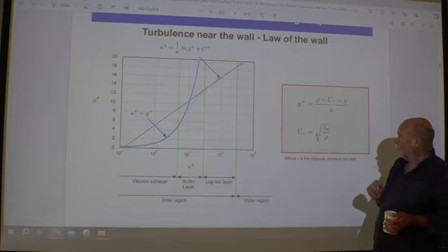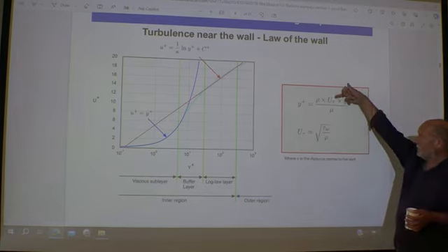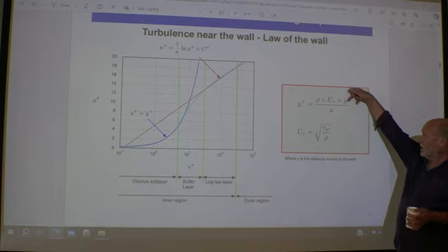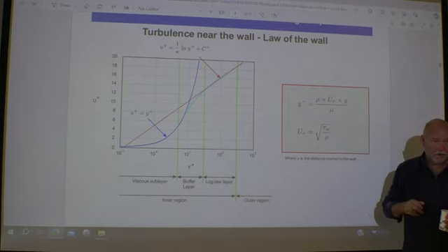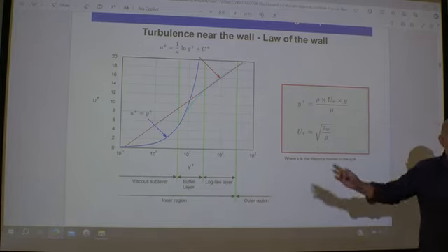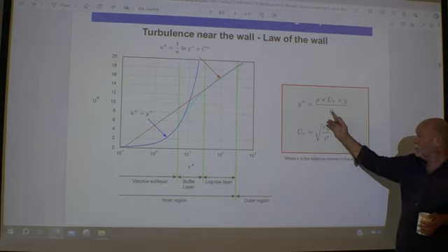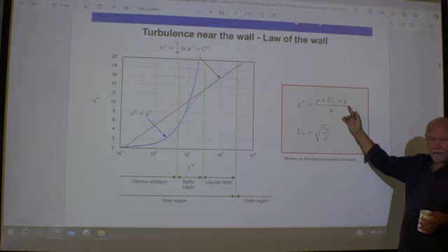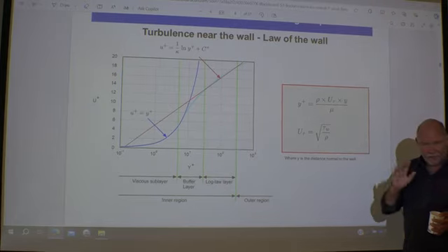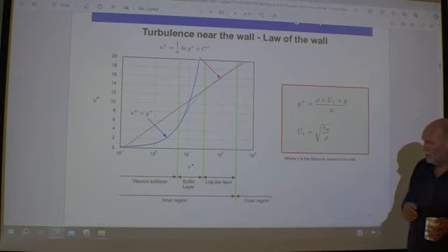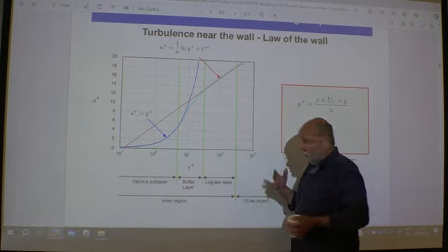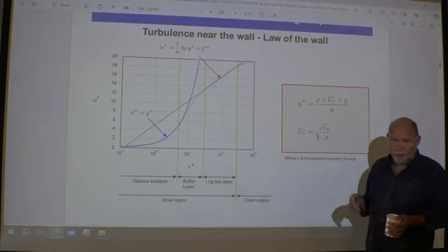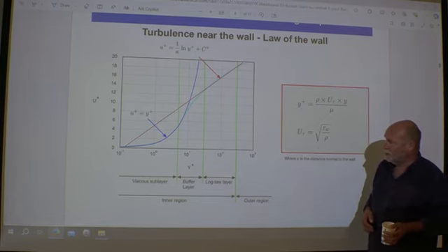Now for the y plus. You see we use this velocity scale here. And then you have the distance perpendicular to the wall in meters, then divided by the ordinary molecular viscosity. You see this is a local Reynolds number with a velocity scale and a length scale. So y plus, think of it as a local Reynolds number. And that's why you get these numbers for y plus. It's non-dimensional. Reynolds numbers don't have any dimension, so that's fair enough.